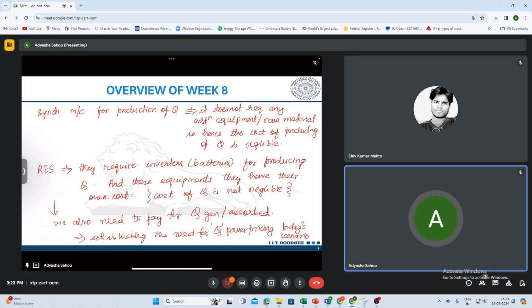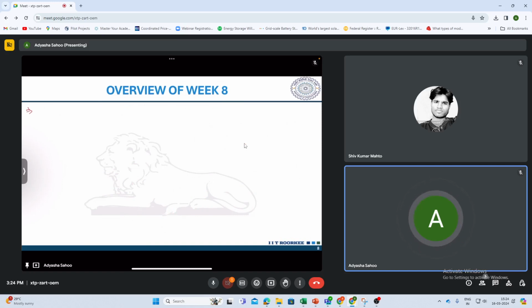Okay, so let us see how we will calculate this voltage stability index. If you remember, while computing method 2 of the load flow, we came across an equation for this voltage, which was biquadratic, right? Was a power 4. So that equation, if I rewrite, it was something like V2 to the power 4, that is the magnitude, plus 2 (P2 R1 plus Q2 X1) minus 0.5 V1 square, multiplied by V2 square, plus (R1 square plus X1 square) into (P2 square plus Q2 square), right?